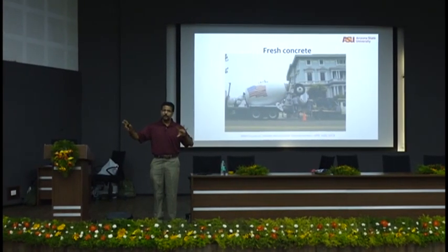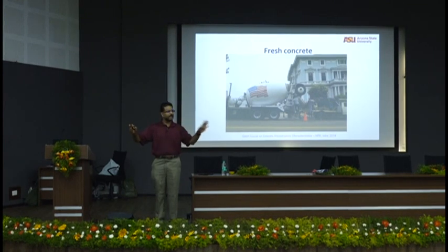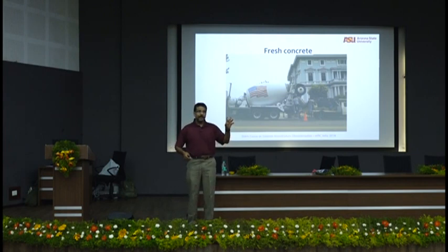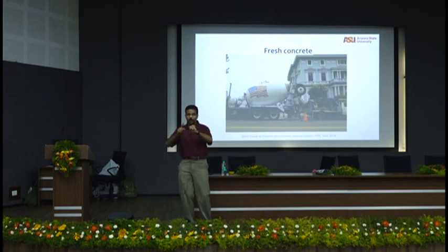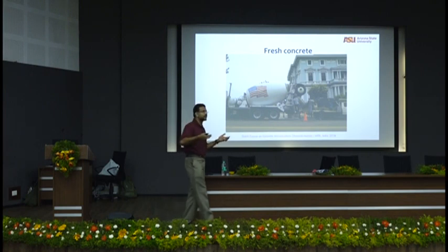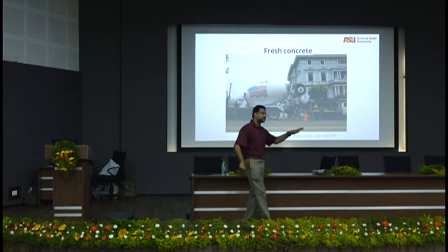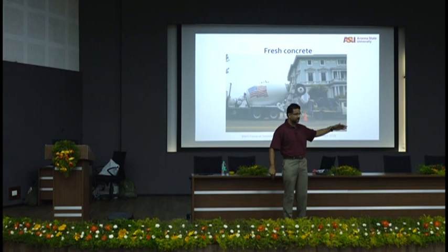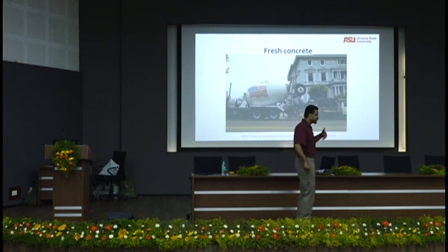Now think of this carefully. When I'm talking about properties, I'm going to talk about mechanical properties and durability. Okay, and that's pretty much what you have in the system. But in the process of structure formation, which influences your properties, there is something else, which is your fresh stage in concrete, right? What happens when the concrete is fresh? Your microstructure forms only after the concrete sets and hardens and forms all the reaction products. So there is a fresh stage.